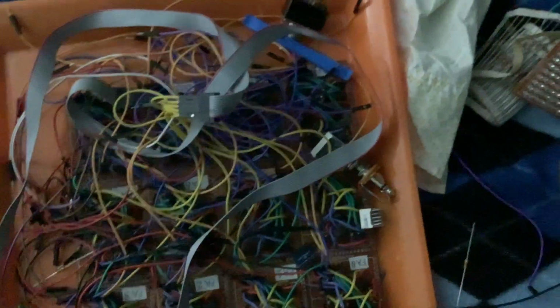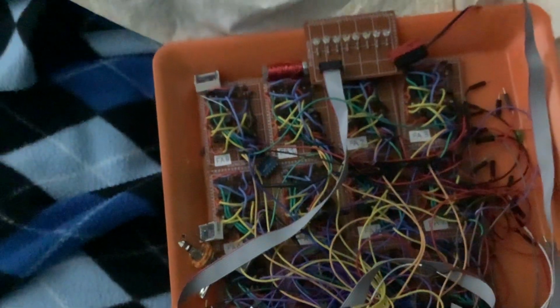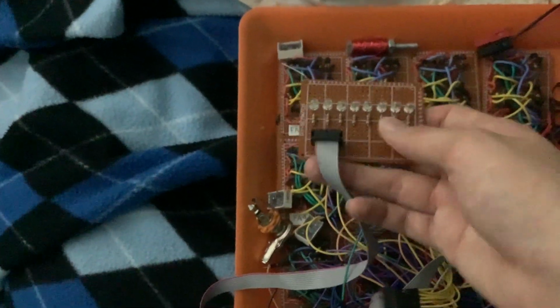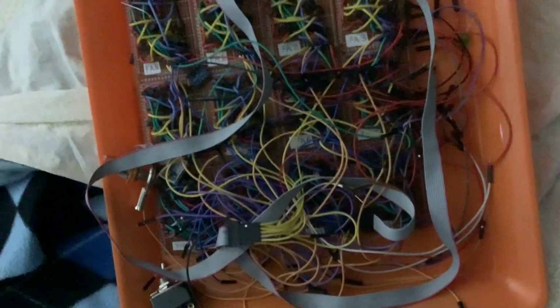And then this is a full adder. It's actually a full adder subtractor. And how you get an adder subtractor is you have all these full adder circuits, and then you have these right here, which are exclusive ORs. If you turn these on, it will transform the adders into a 2's complement subtractor. And the display is just red here. So this itself is actually an arithmetic logic unit. It's missing some key features, particularly it just adds and subtracts, and you really want bitwise operators.